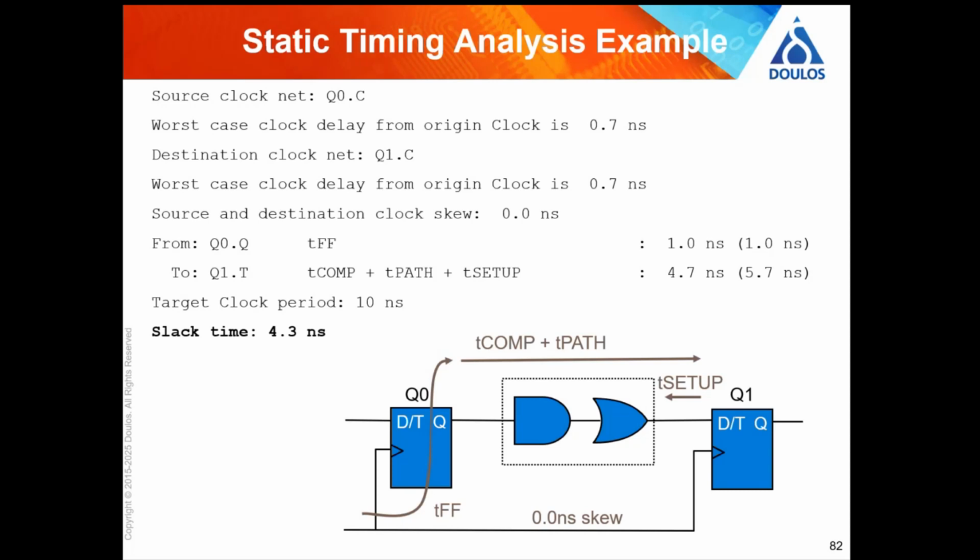And hopefully most of them are all right, but if some of them are not right, then it will output a table saying, well, all of these delays add up, and they add up to 20.1 nanoseconds, but your clock period is only 20 nanoseconds, matey, and so you've got a problem. And so that's a sort of low-level thing, but we're not executing any code now. This is static. We weren't executing any code when we did the logical equivalence checking or the sequential equivalence checking.